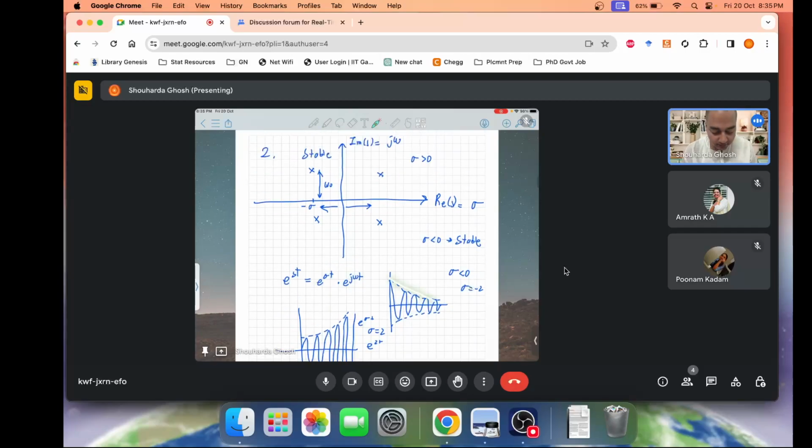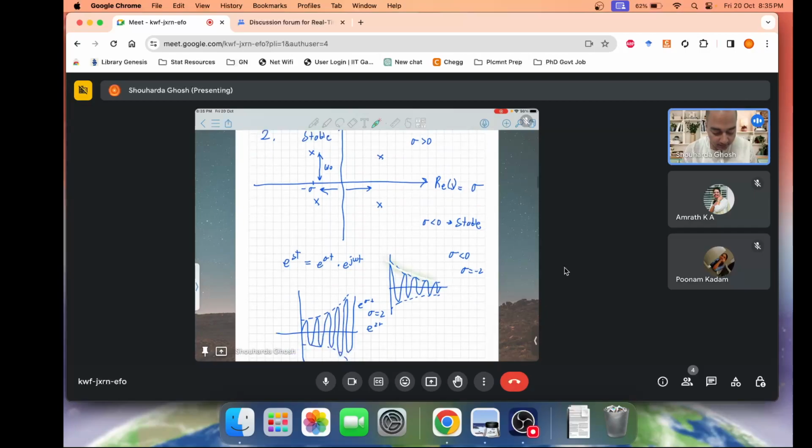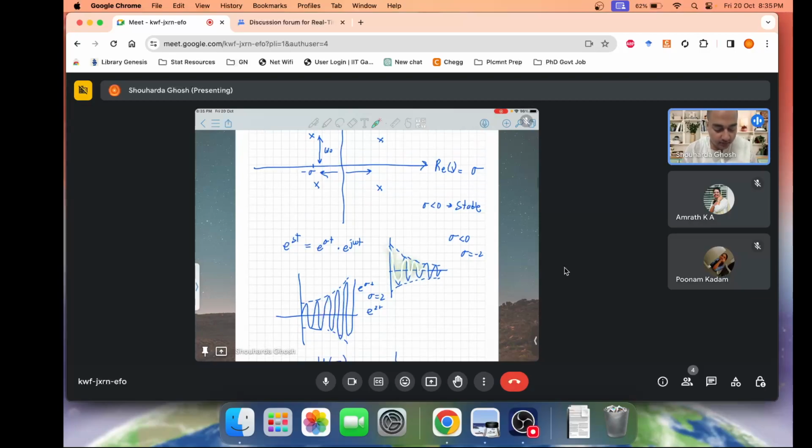If you're on the left half of the S plane, you have a decaying envelope, and the system impulse response is stable because it keeps going down. The integral over |h(t)| dt is less than infinity. So in fact it is BIBO stable.